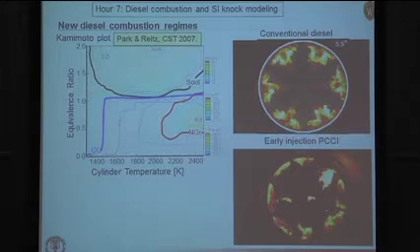So here are some pictures of diesel sprays. This is actually from Chuck Miller at Sandia. One of the things you notice, of course, is a lot of luminosity because of the soot, as we spoke about last time. And this is a picture of conventional diesel. You can see the liquid here. It's still injecting. You can see where the flame is established, and then this downstream region where the soot is being produced.